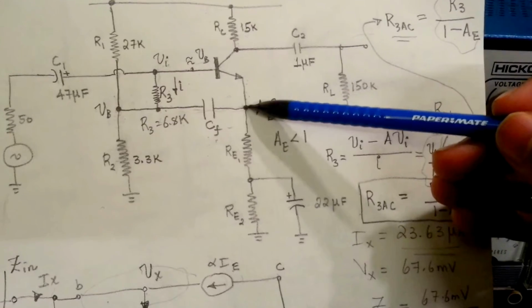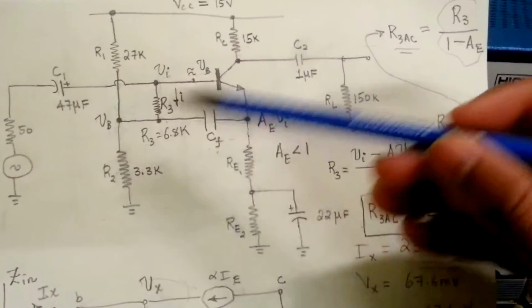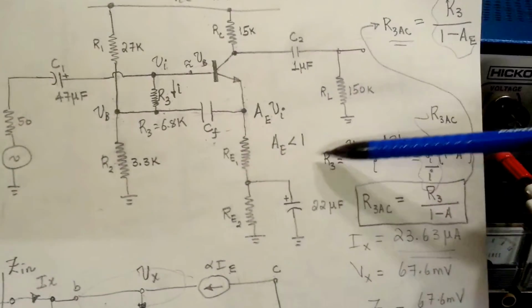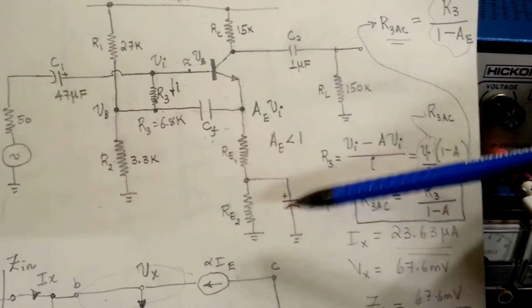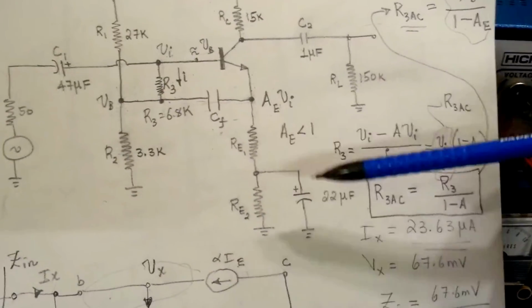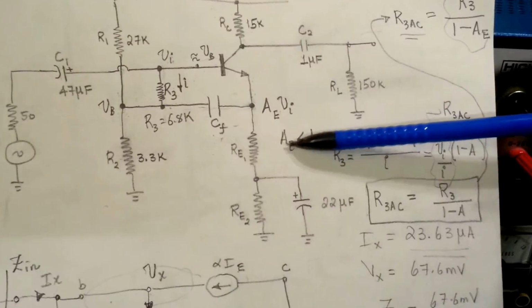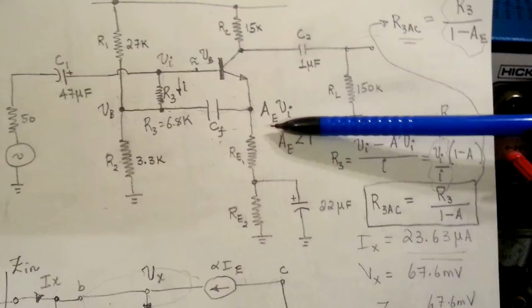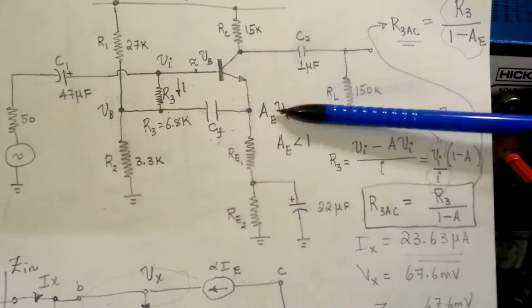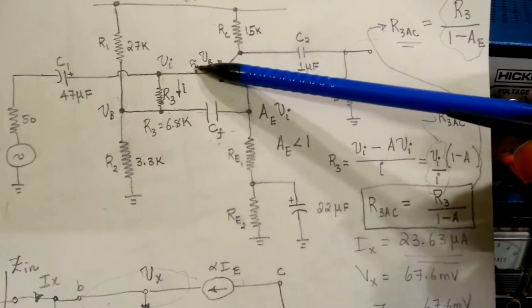So the feedback signal is not going to create an oscillator because the gain is less than 1. There are two conditions you have to meet to create an oscillator: one is the gain condition and the other is the phase condition. But in this case, the gain condition is less than 1, so we're not going to create an oscillator. Because of that, it works to our advantage.